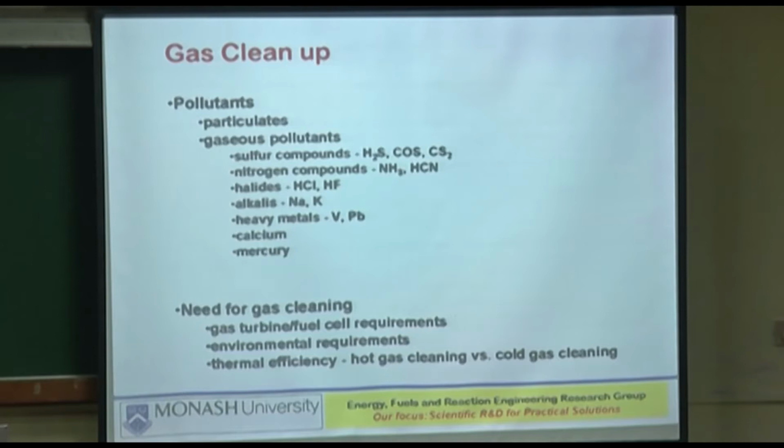So Eastman Kodak developed an activated carbon bed based mercury capture process back in the 80s, and that was demonstrated successfully, and that is predominantly the method now used for mercury, through adsorption onto the activated carbon bed. How you then dispose of the mercury-saturated activated carbon bed, that's a different issue. But at least it's gone from the gas phase.